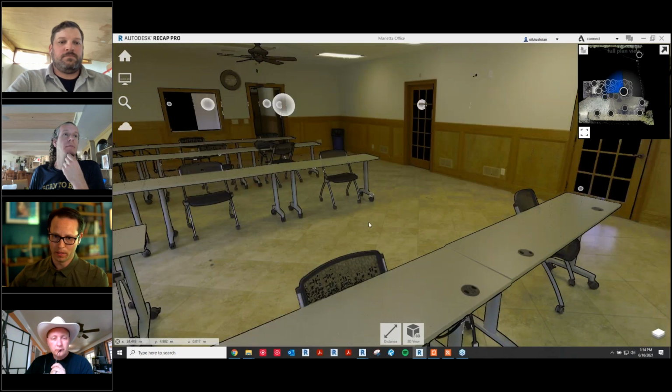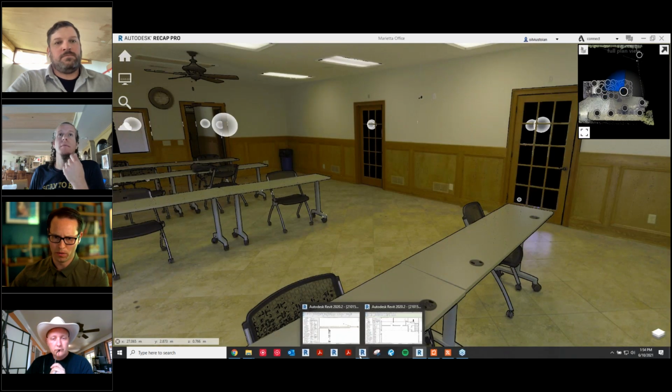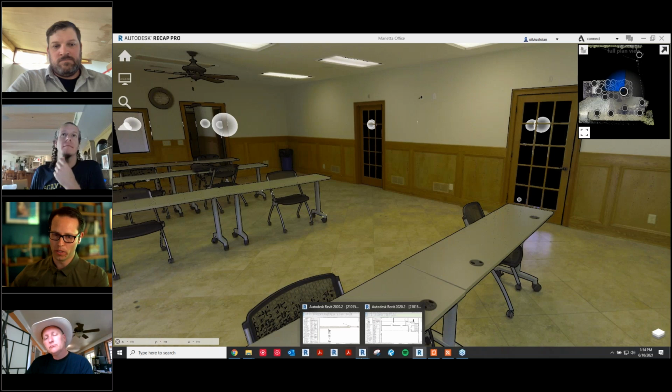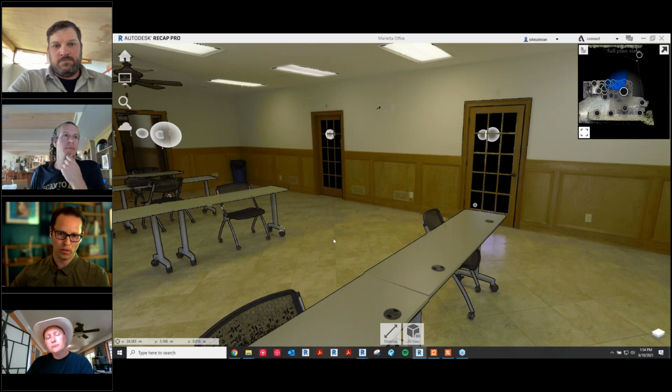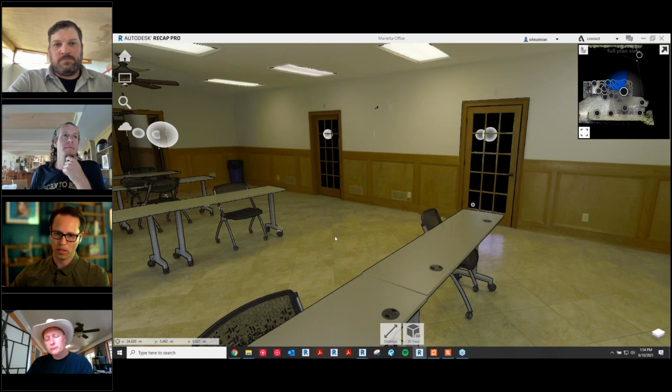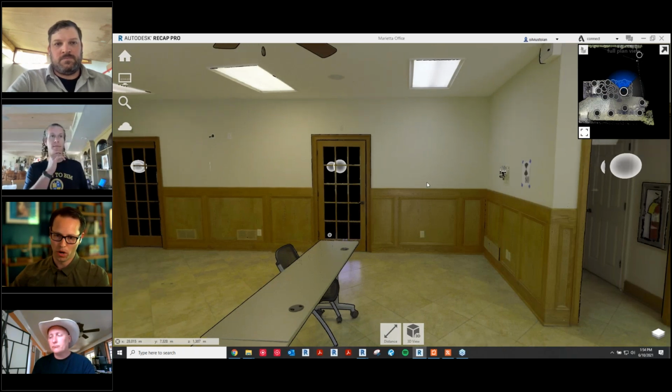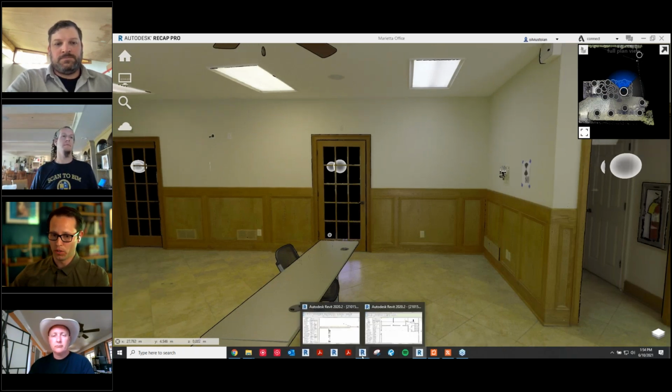This is something that I think, Kelly, we were supposed to cover, but I think we forgot, is the way we build the models, existing condition models. We try to follow the sequence of work that mimics the construction of the building, right? So you first model your structure, and then you enclose the building. You model your partition walls. Finishes always go last. There are situations where it makes a lot of sense to first model the envelope, because